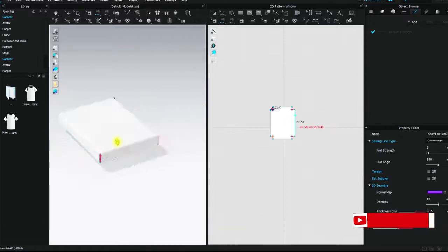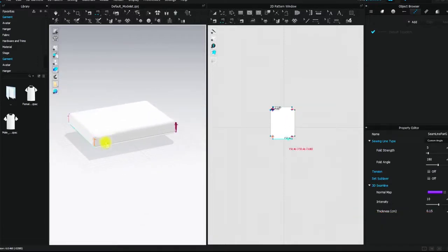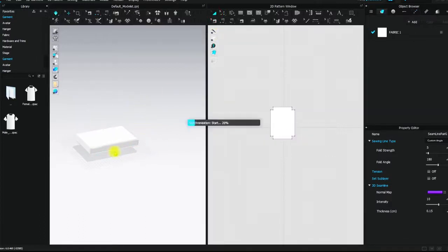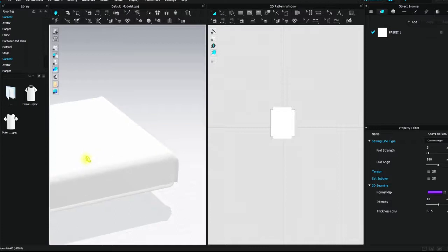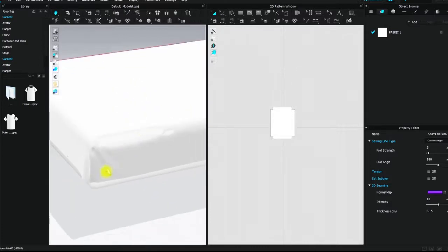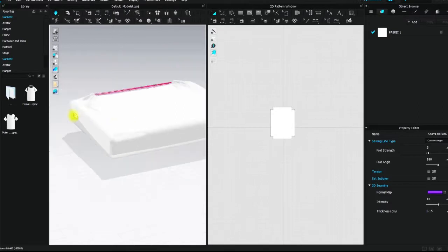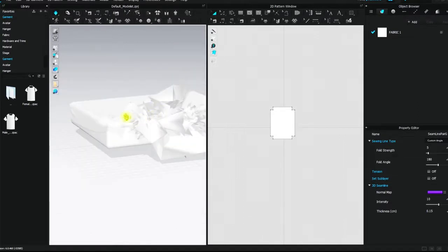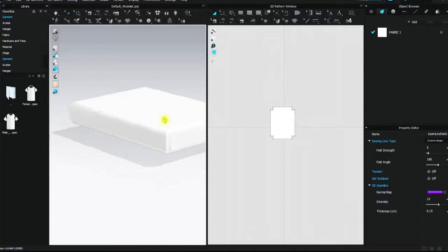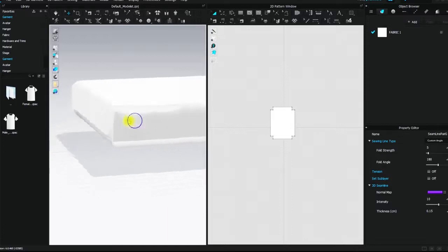So everything is sewn, which I can tell by seeing this red icon. If I go back to this and hit spacebar, it's going to sew everything, and we have that. So if you feel that it's trying to bring everything in, okay, I think I'm going to undo, Ctrl Z. I've mistakenly sewed something. So this is where I have the issue.